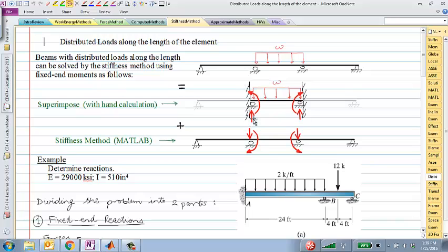As soon as I say that this span is fixed, no matter what loading, we've frozen the rest of the spans of this structure. And what we'll do is read off those fixed end moments from those tables, and we will apply the equal and opposite moment to the problem that we can solve in MATLAB.